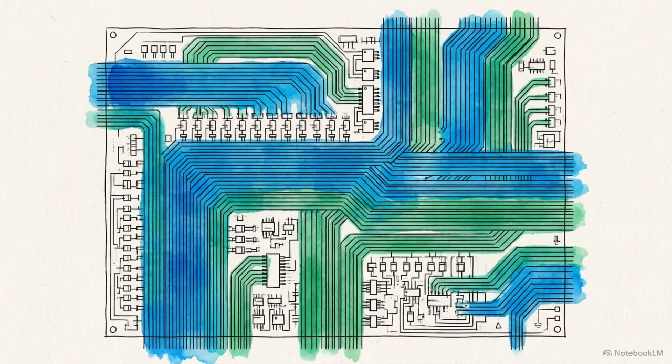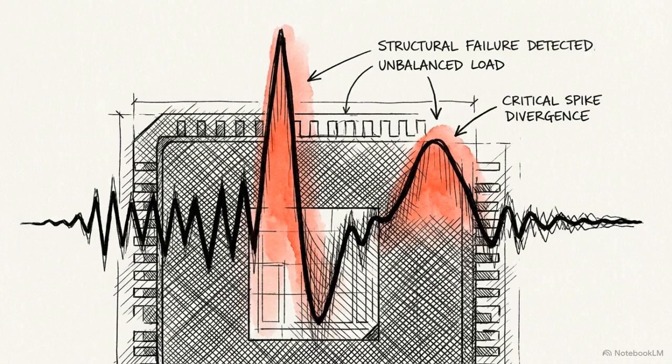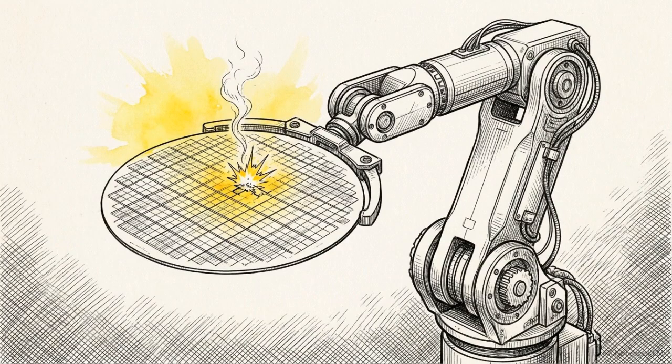Engineers try to mitigate these imbalances using massive layout overheads like backend duplication and fat wire routing methods. They manually force parallel routing to match wire lengths as closely as physics allows, ballooning the physical size of the chip in the process. Even with these heavy interventions, hiding ultimately fails against high-resolution differential power analysis. Human manufacturing simply cannot achieve the flawless physical perfection required to silence the leakage.